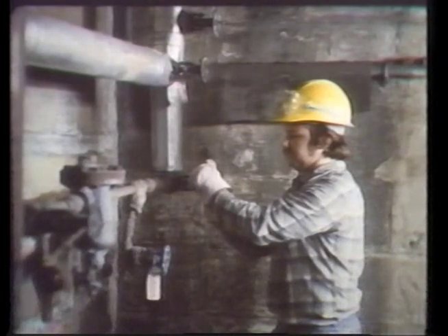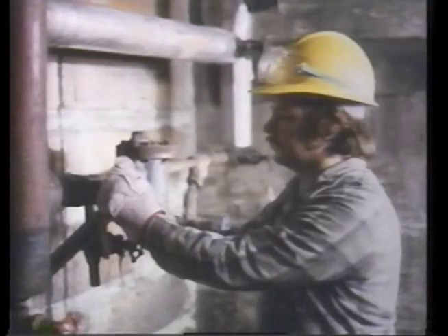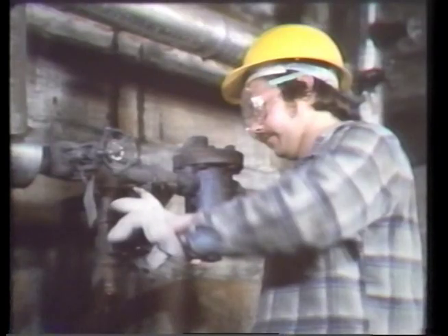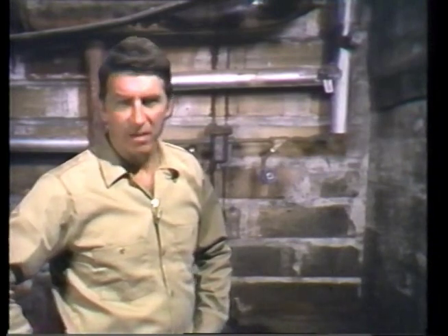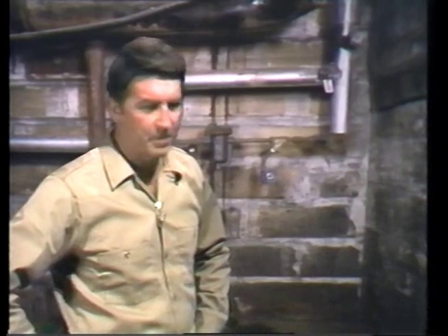Verify that the inlet valve is open. Make sure the outlet valve is also open. Then open the test connection and see if the trap is cycling properly. And finally, blow the strainer down to make sure it's not clogged. If, after performing these checks, inlet temperature is still low, you'll have to take temperature measurements upstream of the trap until you get a reading within the allowable limits.